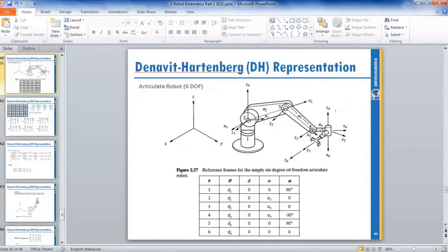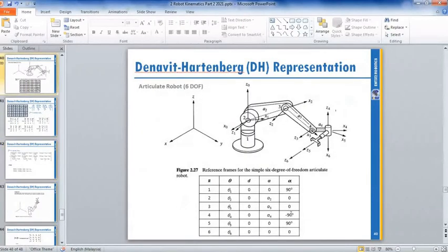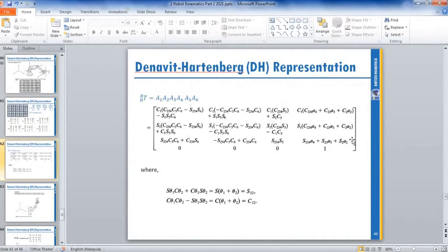If you design your robotic arm or gripper and one changes to another direction, then you cannot apply this formula, because your alpha rotation on the x axis is already different. You cannot apply the formula that you get. So you need to calculate again to get this single matrix for your robot controller.